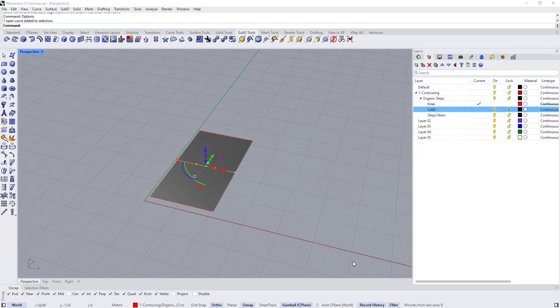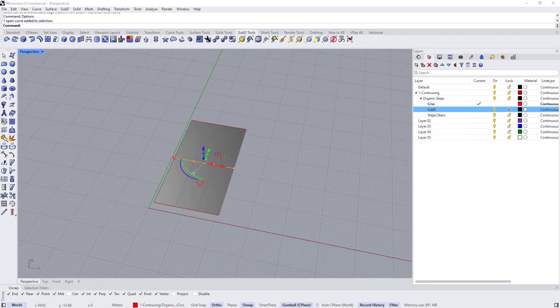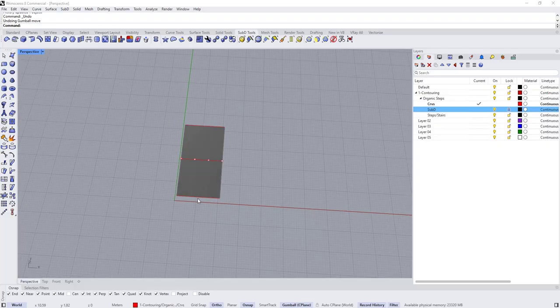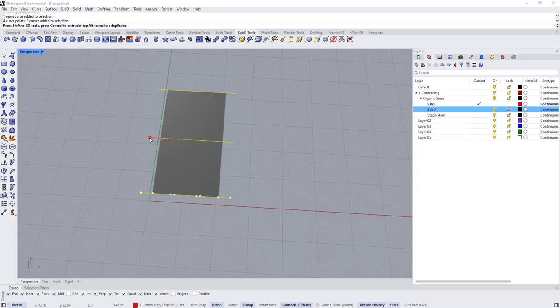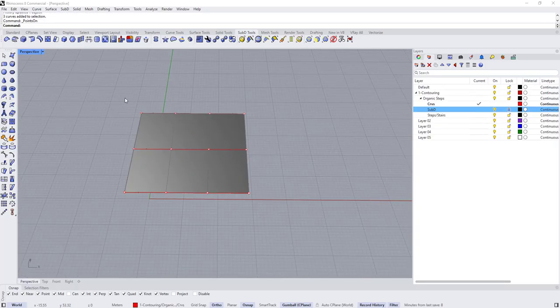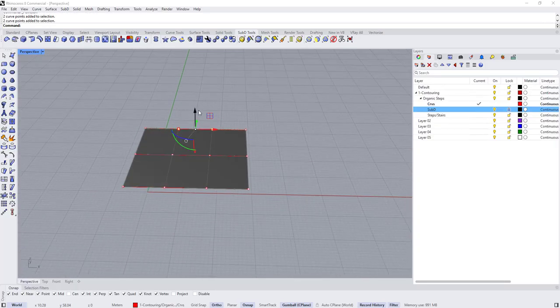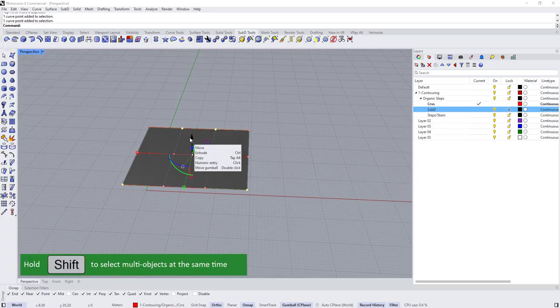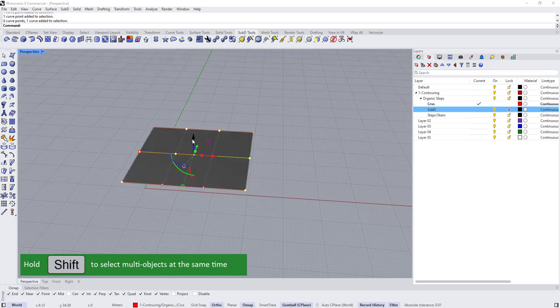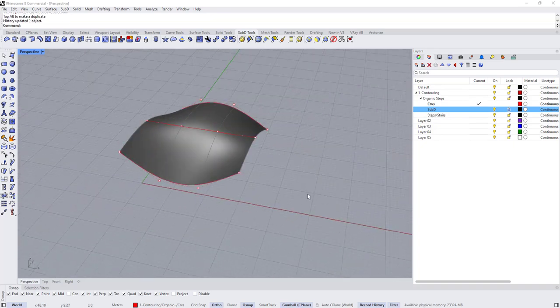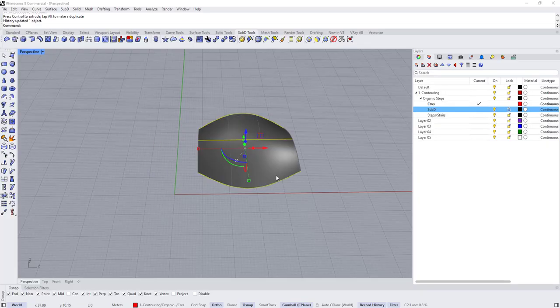This is better. So now, since when we created this SubD surface record history was on, when we start adjusting these curves, the SubD surface will update. I will start maybe by scaling them like this, and then select all the curves, press F10. Let's maybe move these 2 points up, and I'm going to hold shift and select these 2, and hold shift and select all this whole curve and move this maybe something like this by a distance of maybe 8 meters to have something like this.